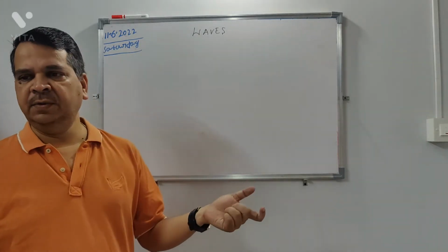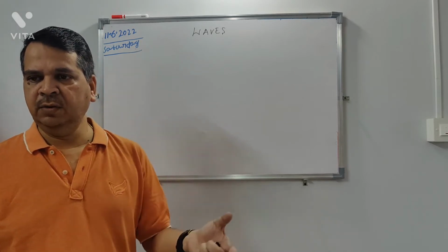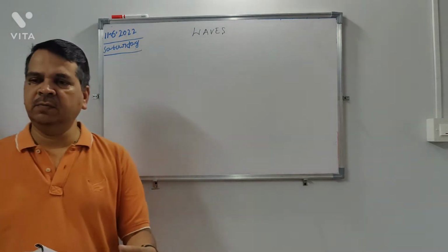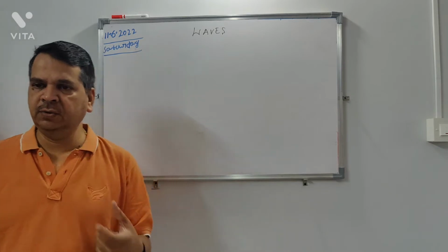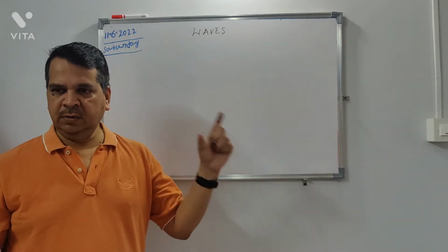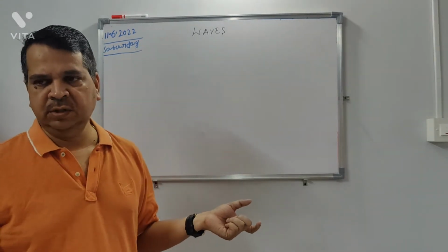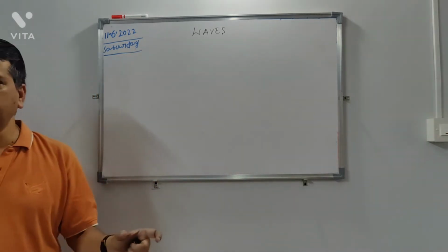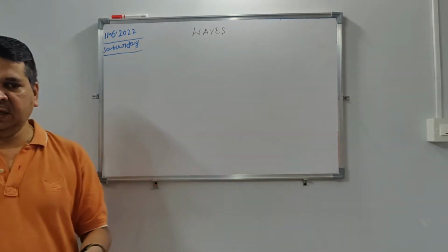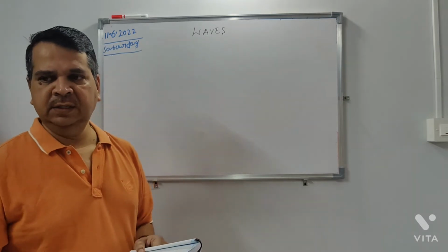Similarly, in case of a heat engine, your work done is the intended thing. So you are taking work done divided by heat input. Okay. So work done is equal to Q1 minus Q2. Q1 is the heat input, Q2 is the heat output. So work done by heat input. Input is your fuel, the calorific value of the fuel times the mass of the fuel, that is your Q1. Okay, that is getting converted to mechanical work. So mechanical work done divided by heat input. So that is Q1 minus Q2 by Q1. So that is the efficiency of a heat engine.